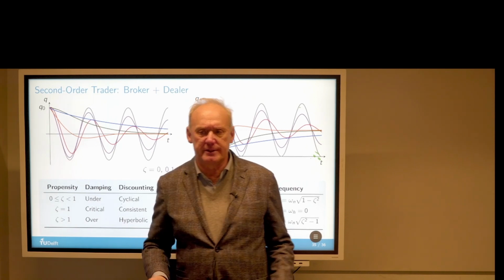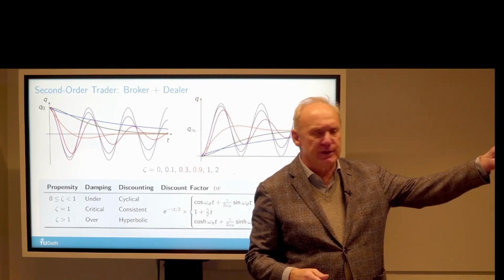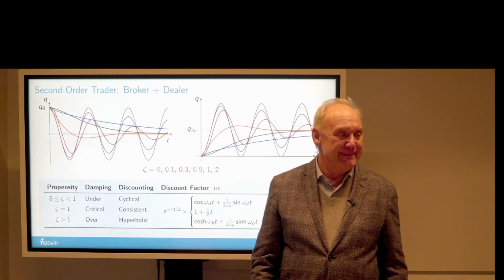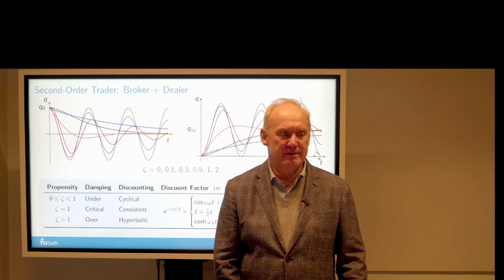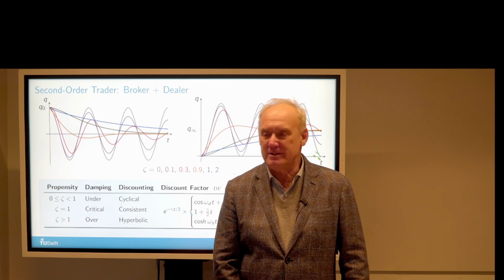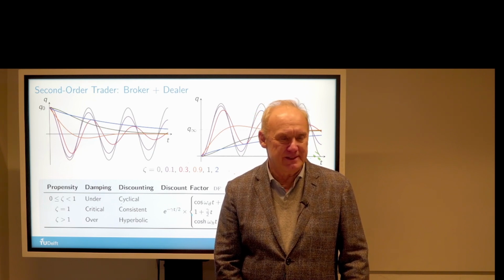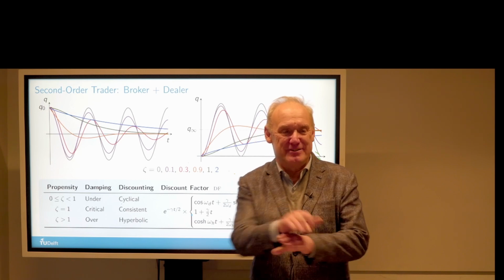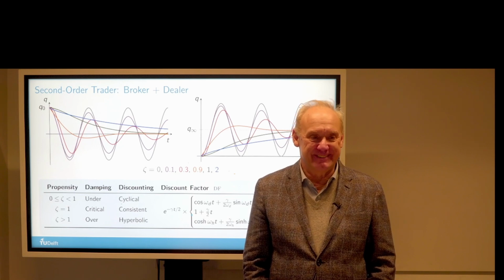This is very familiar, isn't it? So when you use critical damping is when you have a door closer like this. You don't want it to slam, right? If you have saloon doors, you'll let it slam. And then when do you use an overdamped system? Does anybody know? When would you use that? In engineering? No? Critically damped, you know, right? So that gives you the fastest response with no overshoot, right?